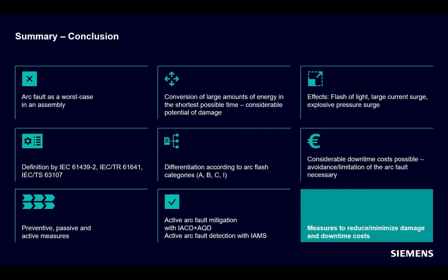If the quenching device is also used, the arc fault can be cleared in less than 5 milliseconds by a short circuit of the main busbar. This further reduces the stress on the system and further minimizes the impact.